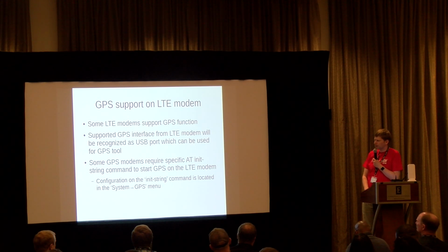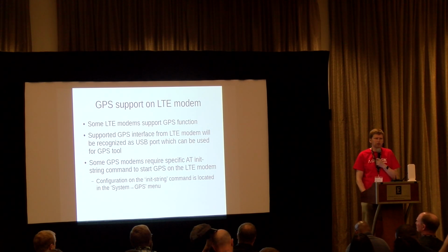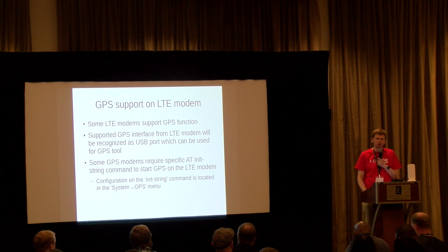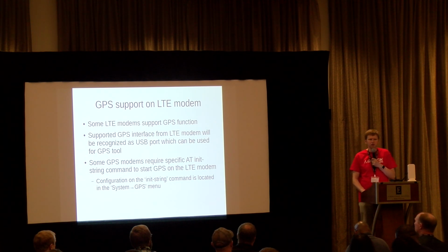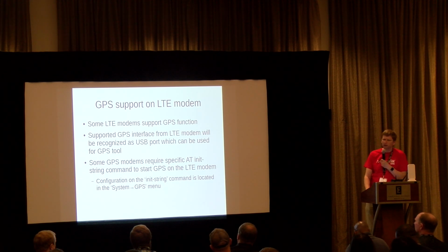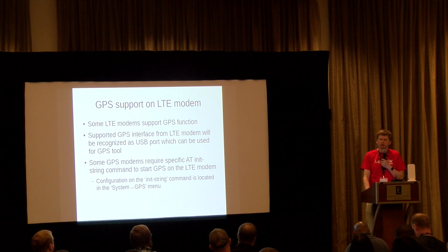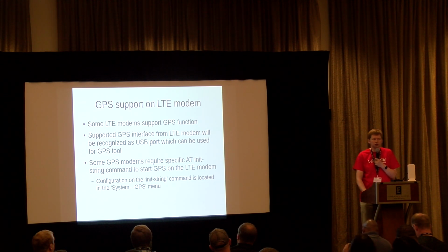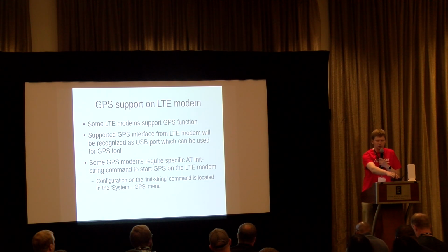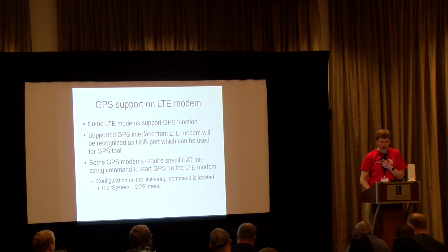But since some LTE modems require additional initial strings to enable that, we have a special command called init_string in the system GPS menu, where you specify some specific AT command that enables the GPS tool. That string could be different because each modem manufacturer has different init strings, so you need to look at the documentation. Also on our LTAP mini board that we'll have here, the GPS is not on the modem interface, but integrated in the board, so it can work independent from the modem.